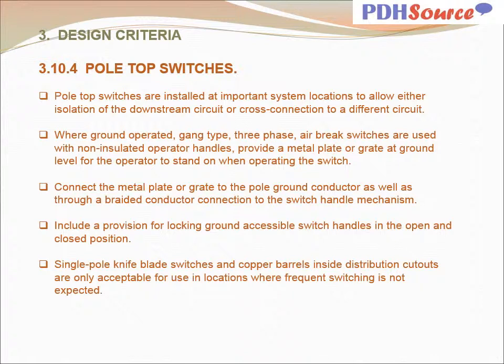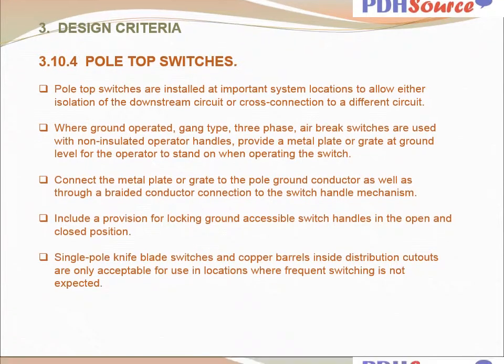Single pole knife blade switches and copper barrels inside distribution cutouts are only acceptable for use in locations where frequent switching is not expected.